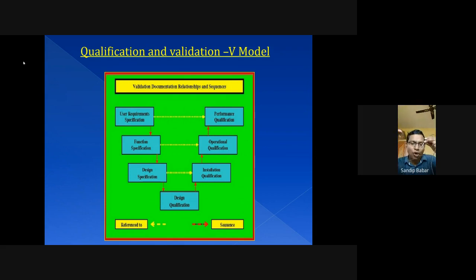You have to log in to that system, similar to our computer. Go to the sequences. We have to select the sequence, pressure hold test. Start. After start, it will ask for parameters. We have to add parameters like pressurization set point 2 bar, stabilization set point 5 minutes, pressure acceptance criteria not more than 0.1 bar. Then if you continue, the test will start.